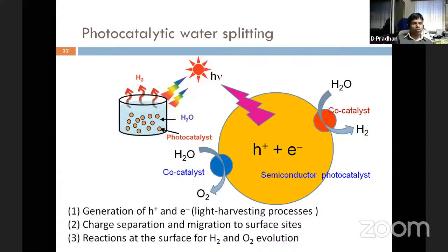On the other hand, in an insulator the valence band and conduction band are far away from each other. Semiconductors have their valence band and conduction band close to each other, with a gap of approximately up to 3 or 4 electron volts. If it is a little higher, above 3 electron volts, we say it is a wide band gap semiconductor. If it is less than 1, we say it is a narrow band gap semiconductor.